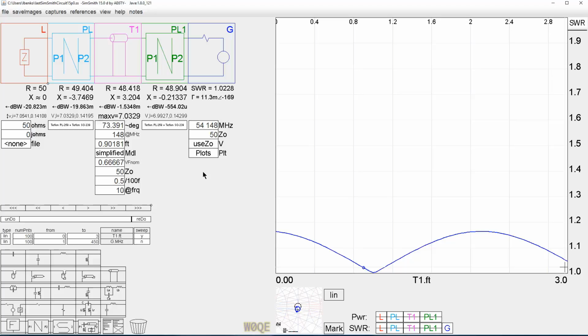Anyways, the advantage of the UHF connector, of course, is a large center pin, which is a lot of contact area, which is good. And the other advantage, of course, is it's inexpensive. It isn't waterproof, and it isn't constant impedance, but it may not matter to you. Anyways, hope this has been interesting.